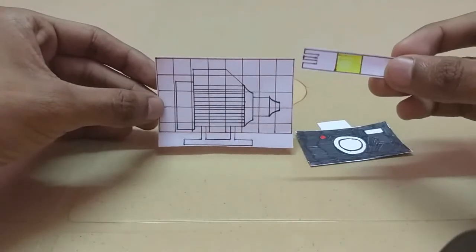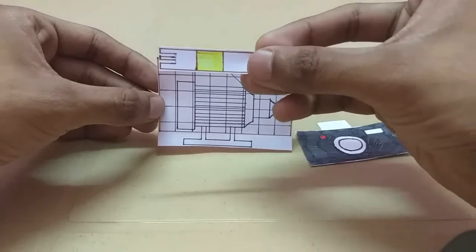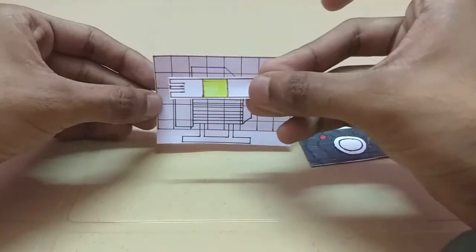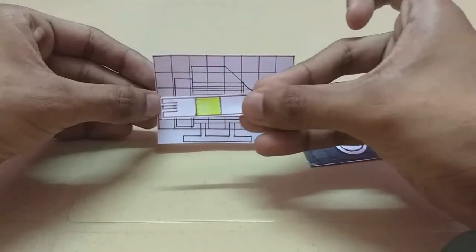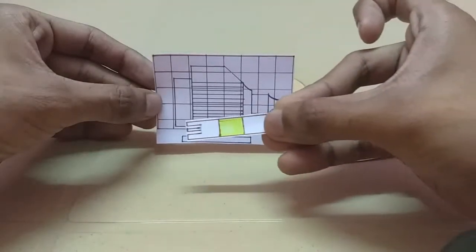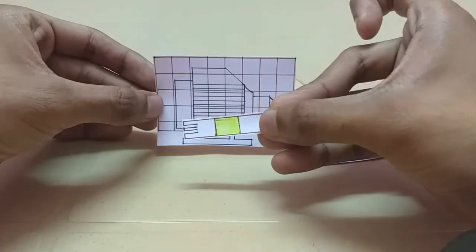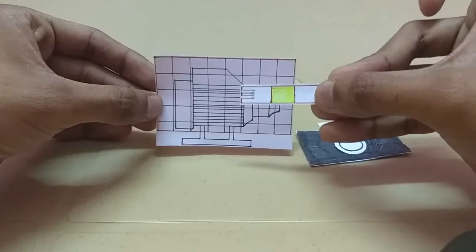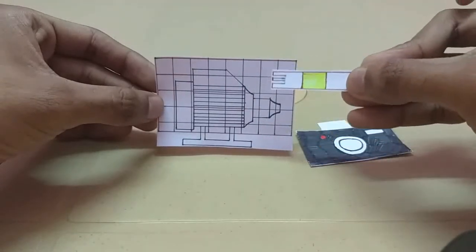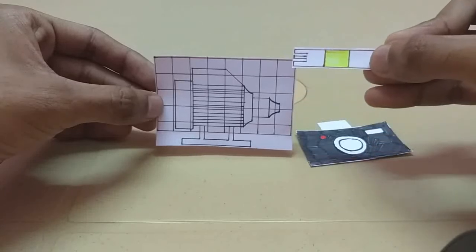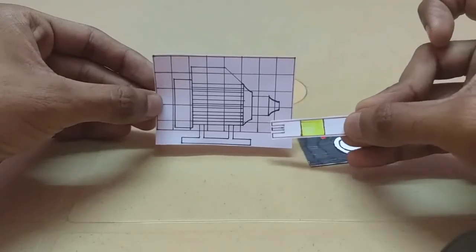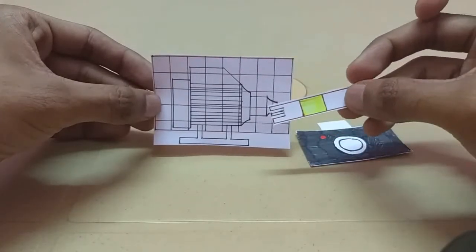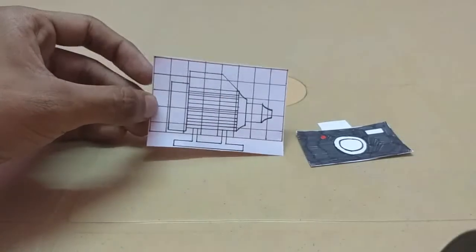During the measurement, the pressure velocity probe is moved along the grid. It is first moved horizontally, covering the entire regions, and then once it's done moving horizontally, it is moved vertically. The purpose of moving along this grid is to ensure that you cover every region, and this will be very useful in determining the sound intensity. Now care must be taken that you don't shake your hand while moving vertically and horizontally. Alright, once you complete moving horizontally and vertically, you press the stop button and your measurement is complete.